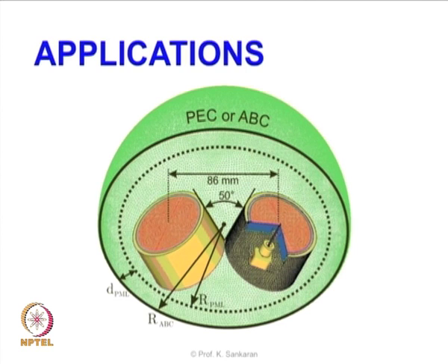In the case of the balloon where the feed is, you are talking about very fine refinement, with 100 cells per lambda, but in the outer areas, where we are just computing for the sake of having the truncation domain far away, we can go for lambda by 10.